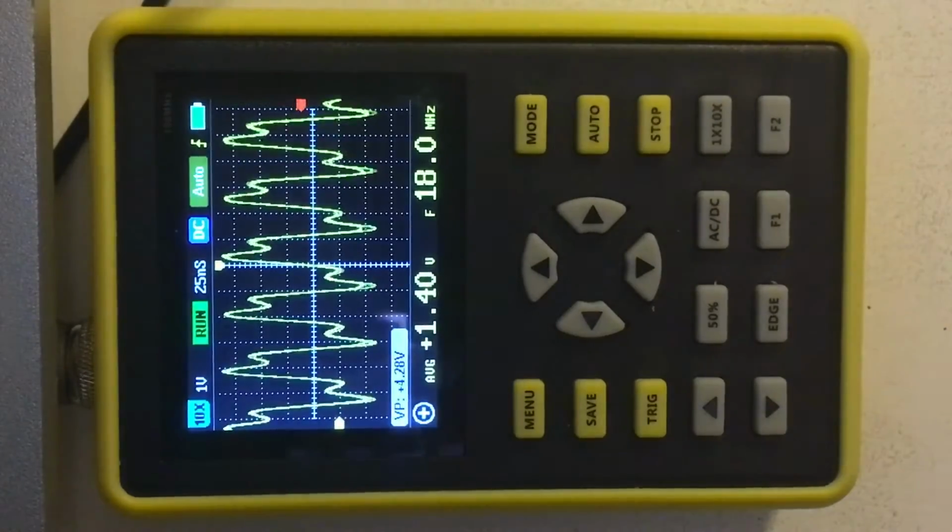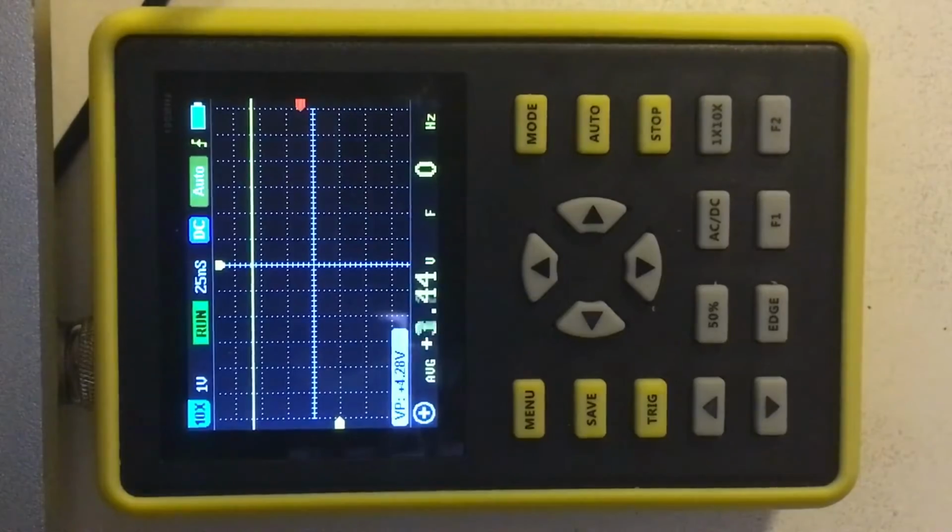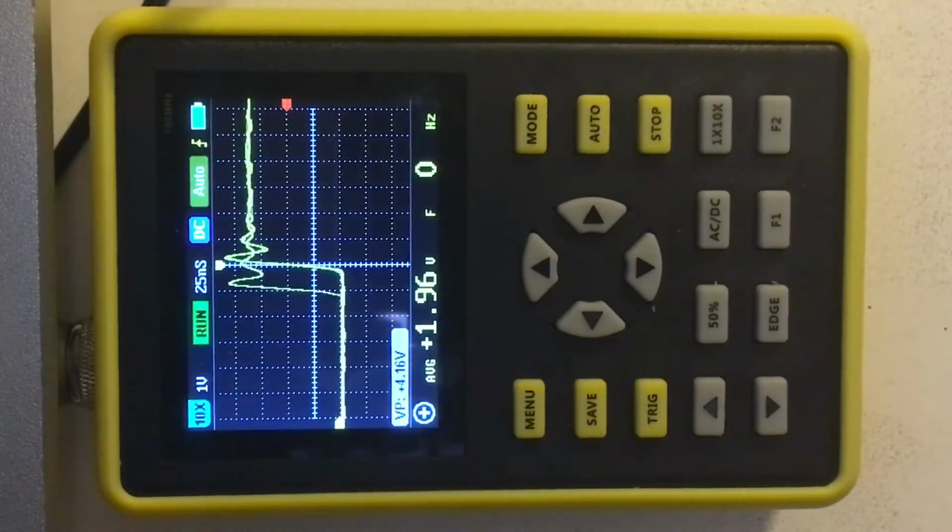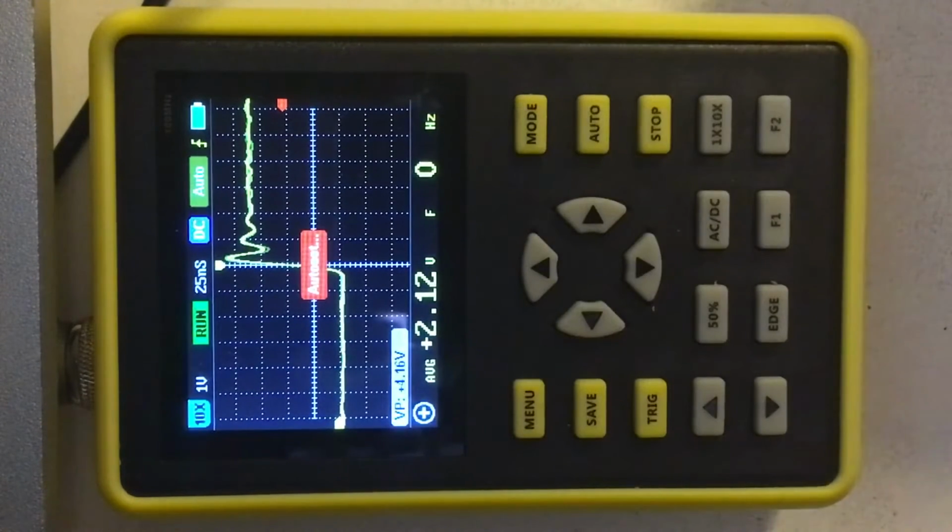But if you push through that and get up past 60, 70 megahertz or something like that, it starts sloping up again. Then by the time you get up around 100 megahertz, you're okay, as long as it's a repetitive sinusoidal type wave. If it's a pulse or a square wave or something like that, it just starts to completely freak out and gives you bonkers answers across the charts depending on what it is that you're measuring.